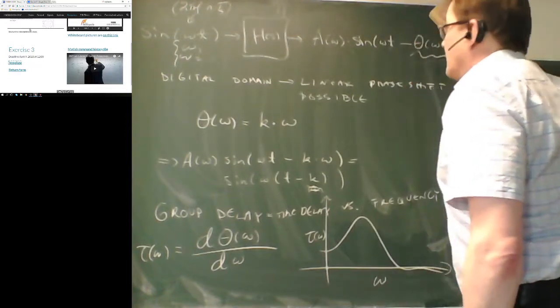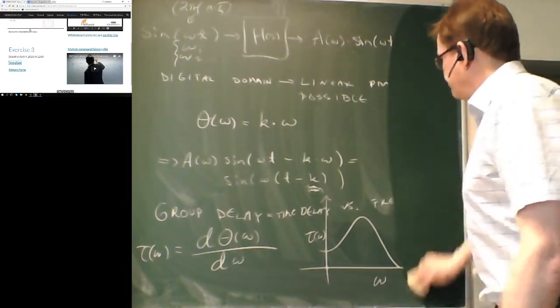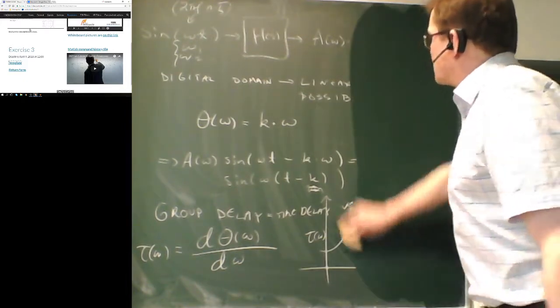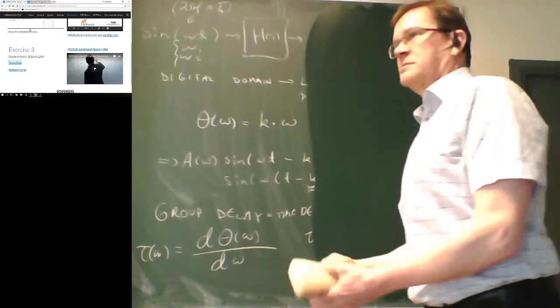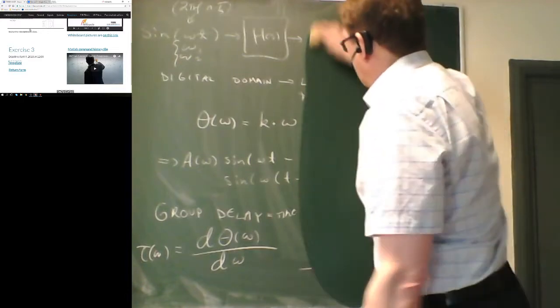Signal spectrum. One more thing: the frequency response is kind of the system spectrum, since you are simply taking your impulse response, making it a transfer function, and evaluating the transfer function at e to j omega. Actually, the signal spectrum is about the same.